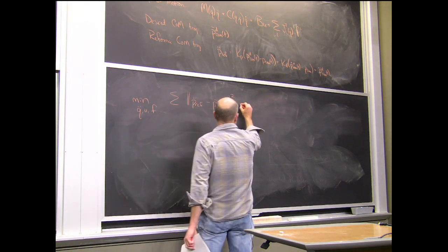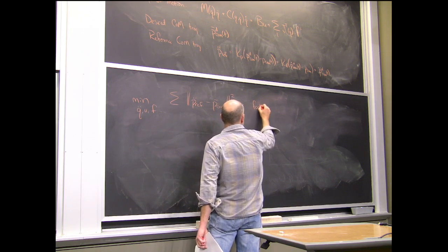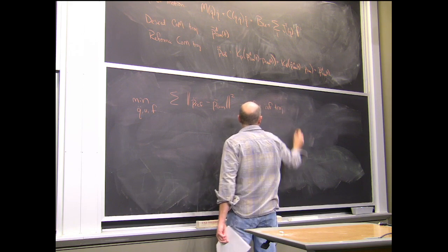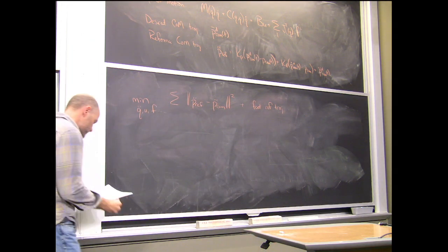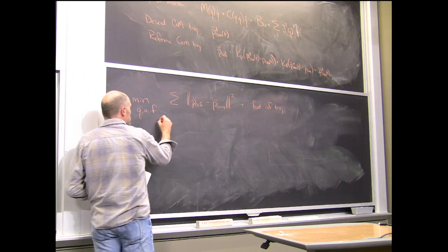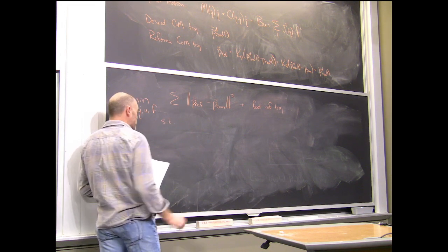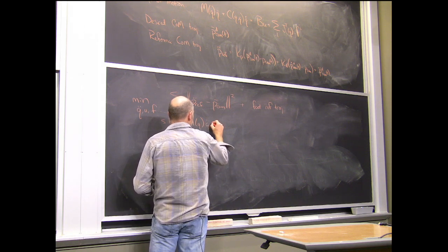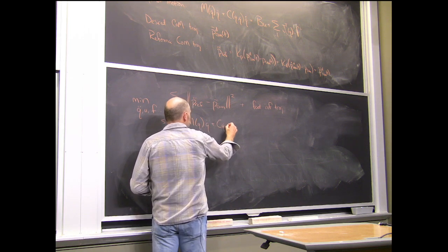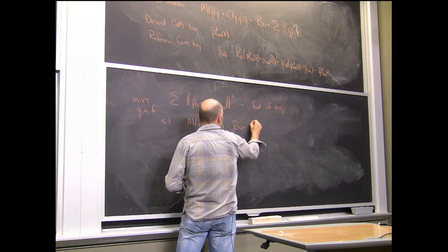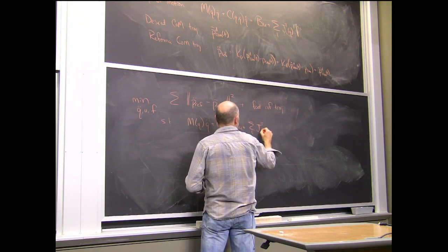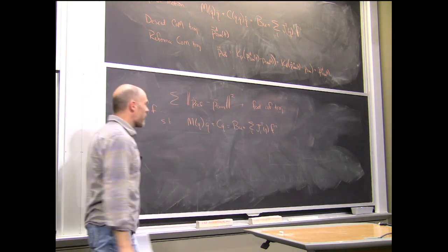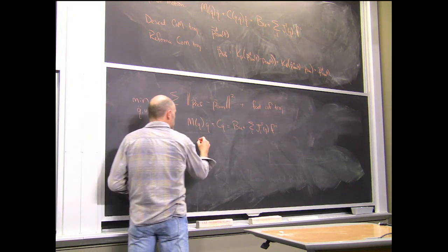I could put in other terms here, like the foot reference trajectory, but I'll focus on the center of mass as the main objective right now. And I do that subject to the dynamic constraints, and subject to the torque limits.